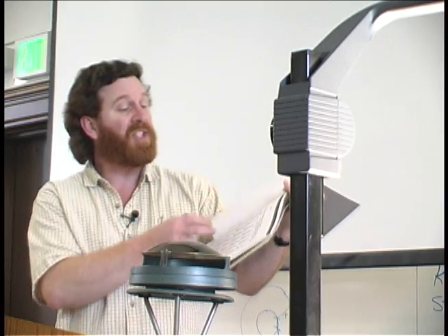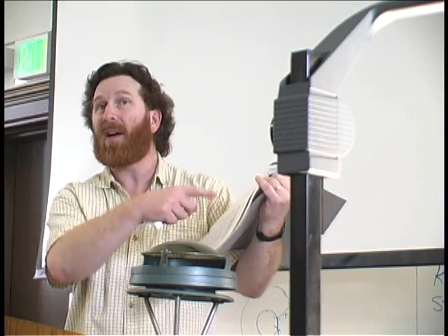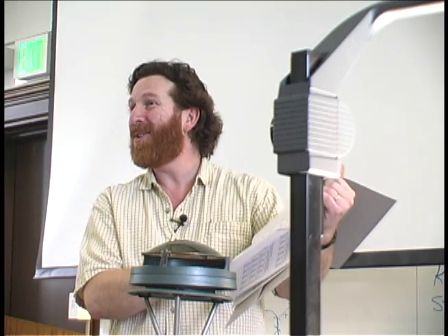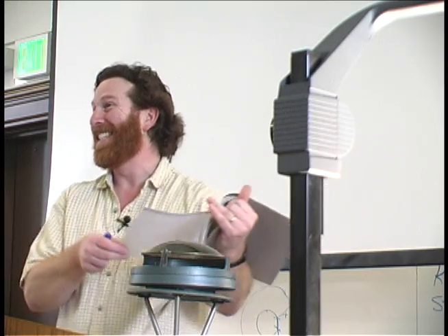And to do the energy trade-off calculation that the state used to require, you needed to do all this. But there's always a couple engineers in the room, and so they're just going, cool, I like this. Normal clear glass, a single pane will let 85% of the whole radiant spectrum through. Low E glass will block out 3 times as much of the shortwave ultraviolet as normal clear glass.